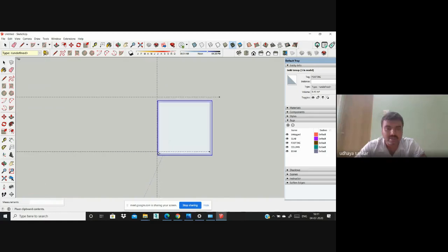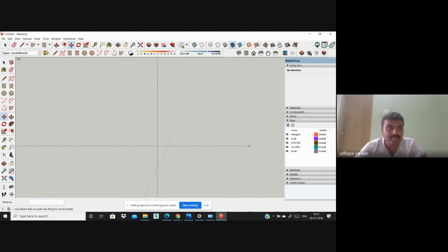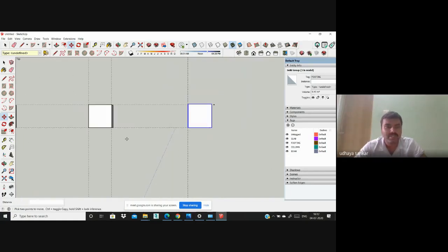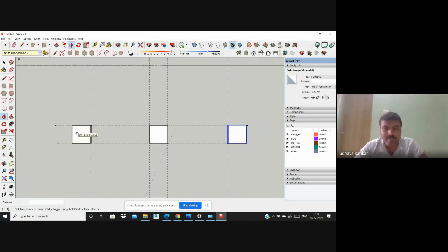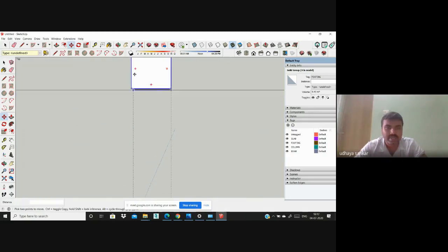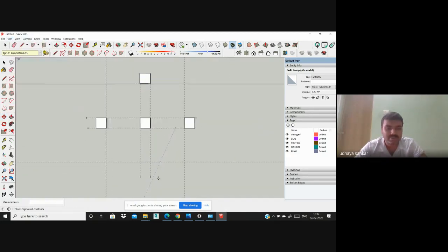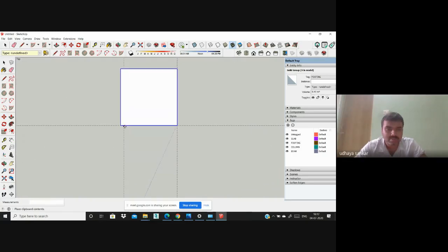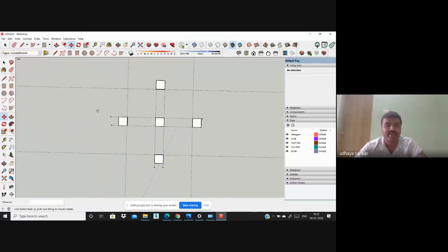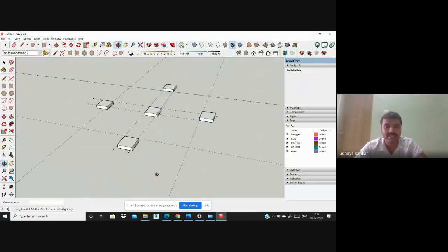I need another footing. Automatically it will be drawn. Simply this one, I need this one type. Simply go for paste, paste again, and another paste. Now automatically it will be created. It will create the 4 footings. Simply create the tags and I have created the 4 footings.